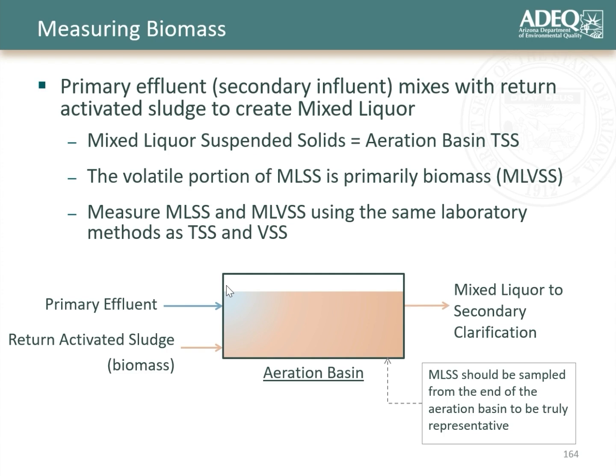You can also do the volatile fraction, similar to the VSS we talked about in earlier modules. Looking at the mixed liquor volatile suspended solids is another way people will measure this. Once again, these are measured the exact same way that you measure TSS and VSS. It's just that you're doing the TSS and VSS sample on the mixed liquor in the aeration basin. One important thing to note is if you're looking to quantify the mixed liquor suspended solids or the MLVSS, as the case may be, you want to collect the sample at the end of the aeration basin to be a good representative sample of the amount of bacteria that's in your system.